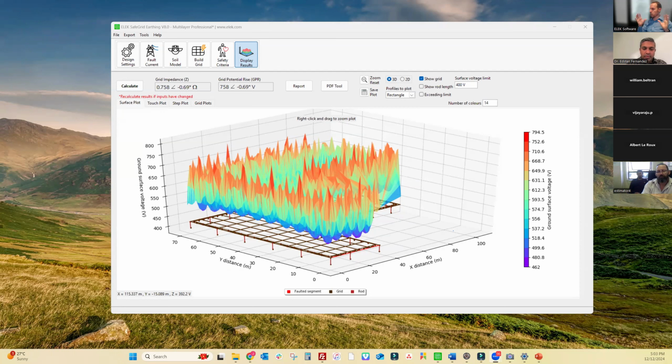So we model the cable, we model the sections, we model the earthing system at the ends and any intermediate earthing systems. We can also model overhead transmission lines. We model all that. It's essentially like a circuit analysis. It becomes like a nodal circuit analysis. We calculate all the voltages and currents. But one value we're really interested in is the voltage that enters the grid.